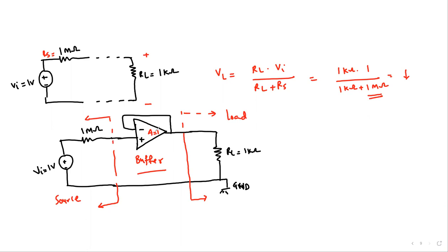So it's a case of non-inverting connection. It acts as a voltage follower. So the output voltage follows the voltage that comes in, without degradation. This buffer provides an input resistance of infinity and an output resistance of 0. We've seen that.